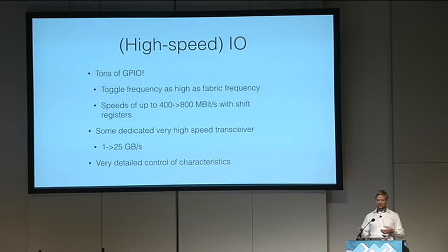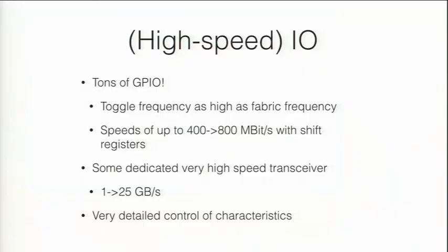Another very cool feature of FPGAs is high-speed I/Os. I was talking about those. You have tons of GPIO. Every pin that you have on the FPGA can run a UART and a SPI bus or I2C, you know what I mean. And the other stuff. Most of the protocols that you can imagine can run on every pin that you have. And those pins are actually pretty fast.